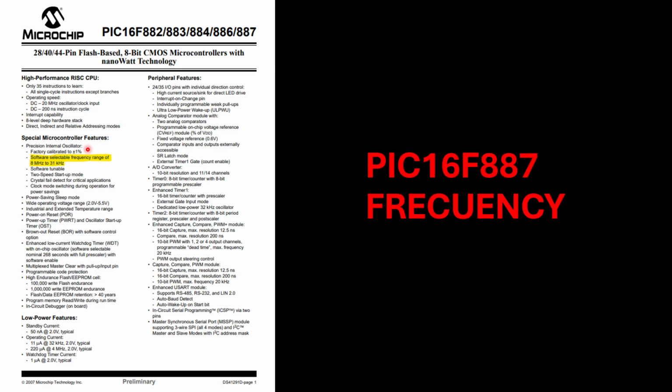You can attach external clocks, right? And then you can even increase this frequency to a higher value. But this time we are not going to use any external clock. We will work with the one that is built into the microcontroller. Okay, so for this example, we are going to choose the highest frequency. It will be 8 megahertz for the following example.